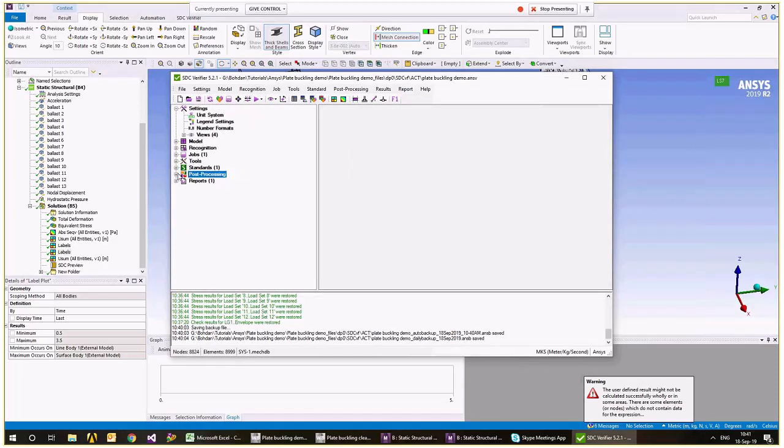Okay, and now let's go to the report. First of all, we have 4 templates for the report. We have the empty one, where you define everything from scratch. We have a model setup report, where you have your model items like properties, materials, their masses, and so on. A results report, where you have tables and plots for stresses and displacement. And the full one, which is based on the results plus model setup report. I have already predefined a report that is based on the full one.